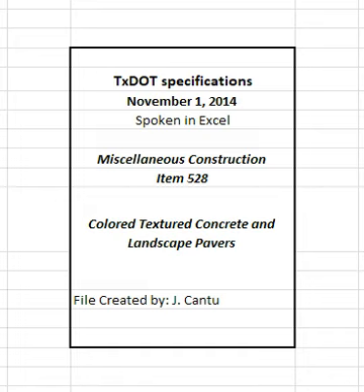To fill smaller edge spaces, use a grout mix matching the color of the pavers that consists of 1 part hydraulic cement to 2 parts concrete sand. Use cement and sand that meet Item 421, Hydraulic Cement Concrete. Do not allow construction traffic on pavers during installation and compaction.